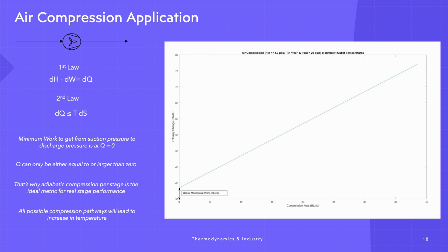When you are trying to compress a gas, for example, the rotor is moving at a given speed, the gas is moving at a given speed. However, the stator, basically the casing of the compressor, is at zero. So there is a differential speed between the gas, the rotor and the stator, and that creates friction, and that's where the heat is coming from.